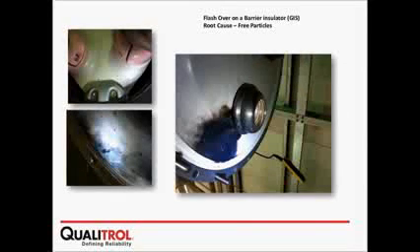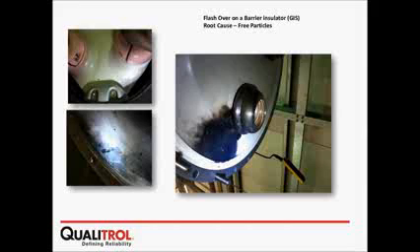Next one was a PD caused by a particle, and it eventually ended in a flashover. A particle will bounce, and we can detect that with partial discharge monitoring as well. If a particle of metal falls in the wrong place, it will lead to a phase to ground or phase to phase failure. In this case, it was a phase to ground failure, and the discharge was over here from phase to ground.